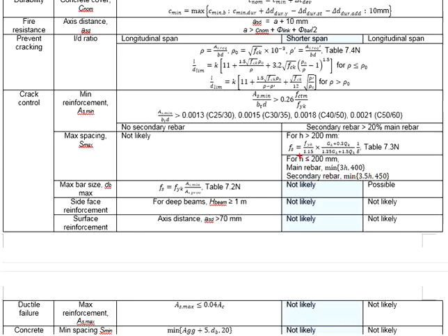In the case that the thickness of the slab and the staircase is less than 200 mm, the maximum spacing is more straightforward. For the main reinforcement bar, the maximum spacing should not exceed 3 times the thickness of the slab or the staircase, and not exceeding 400 mm.